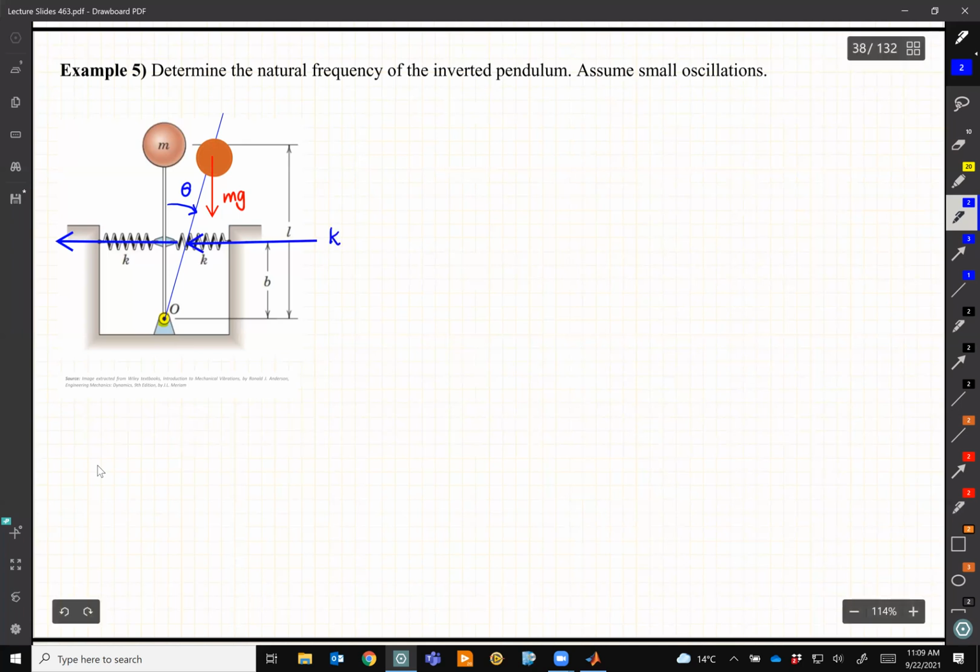And what is their deformation? We talked about it and said that because we are in vibration, the motions are small, so the deflection of this one is going to be b theta, and the deflection of this one is again b theta. So that's my free body diagram. I'm not worried about point O because it's just a point, and we draw it just for the sake of showing the force. In future, if we are interested in designing this pin, maybe we can find OX and OY.